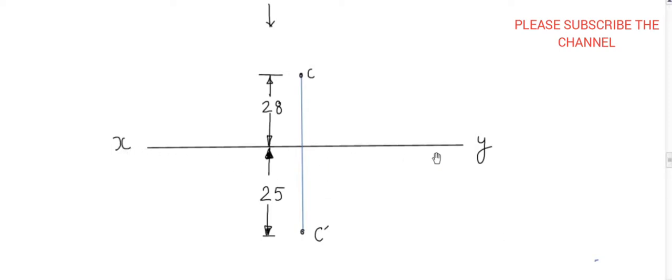Draw a reference line XY, mark a dot 25 mm below, which shows the front view, with the necessary dimension 25 mm. Just above it, 28 mm above the reference line, I mark an internal dot which denotes the top view. This is the necessary dimension and shows the 28 mm. This will be your final solution when the point lies 28 mm behind VP and 25 mm below HP, which is in the third quadrant.